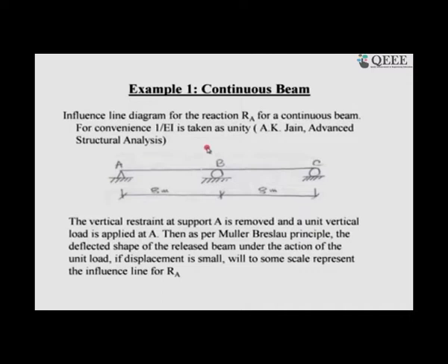I will also tell you later that for statically indeterminate trusses or highly statically indeterminate structures, the advantage of using the Muller-Breslau principle may die out, because if you remove one redundant and try to examine the displaced shape, the other redundants will prevent it from displacing well, where the shape of the curve would otherwise be apparent. So there is a theoretical disadvantage in the experimental determination of influence line diagrams.